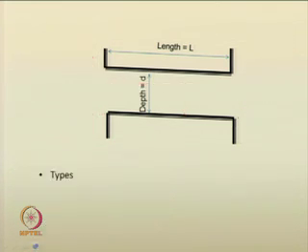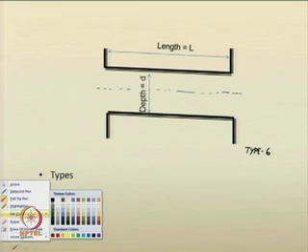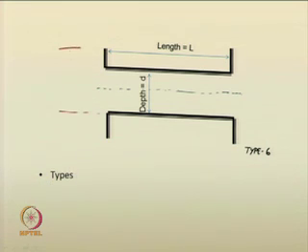So, if you have a definite control here, such mechanisms can be provided, and the flow inside the culvert is also subcritical. Next, the type 6 flow you can discuss is where we can suggest type 6 such a way that, let me draw the critical flow, say if this is the critical flow depth inside this thing, and if this is the headwater depth H. So, we are suggesting H less than H star, and the flow goes all of a sudden into the supercritical form.